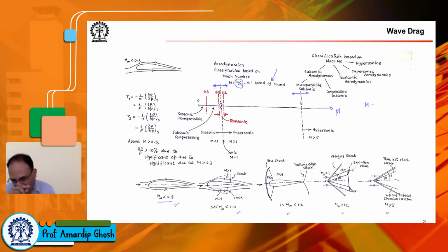Okay, so flow is still subsonic. So free stream Mach number is subsonic. Flow is accelerating here and there on the wing, but if you look all over the flow field over the wing, everywhere it is subsonic, although it can be more than 0.6.